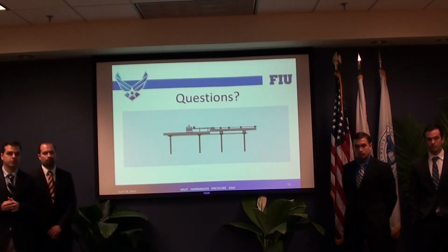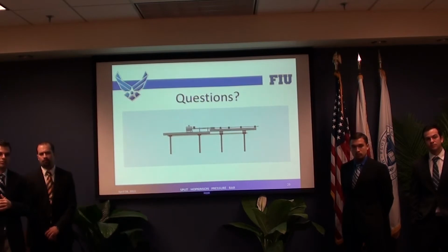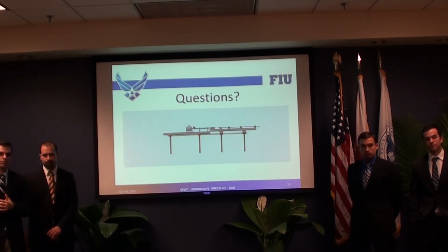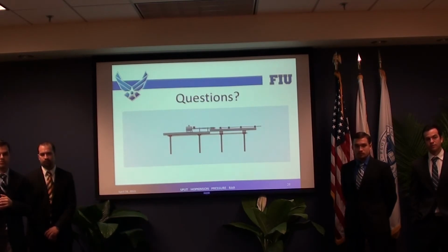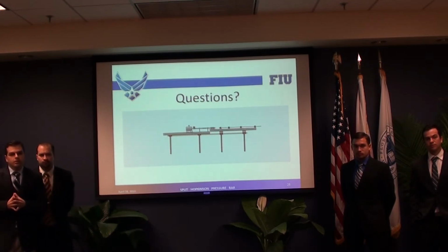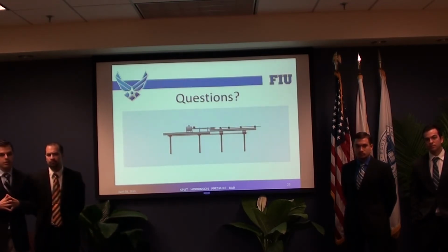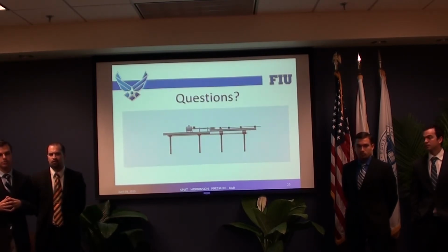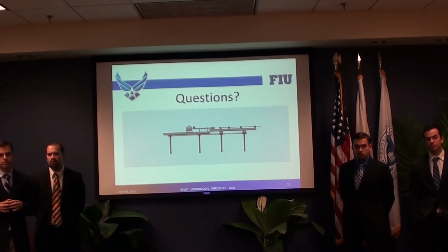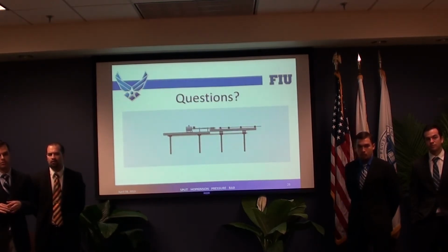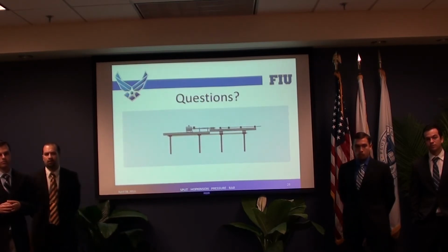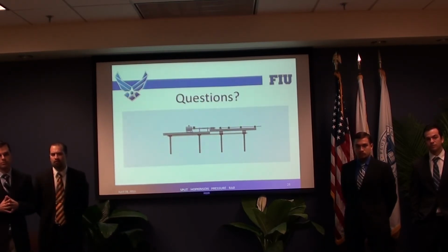There's something you have in your report, in the conclusion, I just want some clarification on. Let me just quote what you have. They said the newly upgraded Hopkinson bar produces a consistent and reproducible striker bar velocity up to 120 feet per second, which furnishes strain rates up to 10^4 inch per second. The diagnostic system implemented upgraded the frequency response of all the components to 100 kilohertz. This is the minimum frequency required to interpret the data clearly without any distortion.